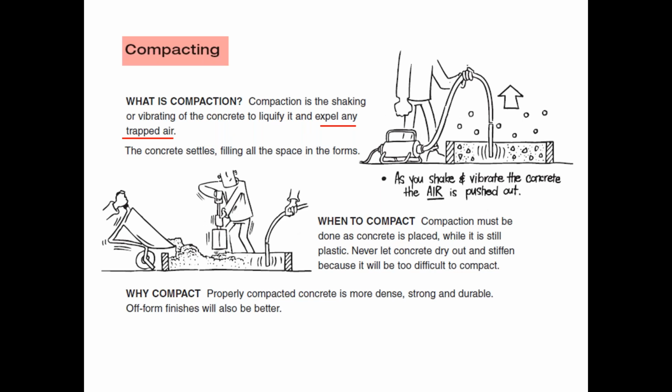So again, compaction when we're laying that floor is critical, and I can't go over this enough, because we need a good, hard, strong floor. You start driving trucks and forklifts with heavy loads over these things, or machinery on top of it, it needs to be compacted well, so we'll get a nice dense concrete floor.